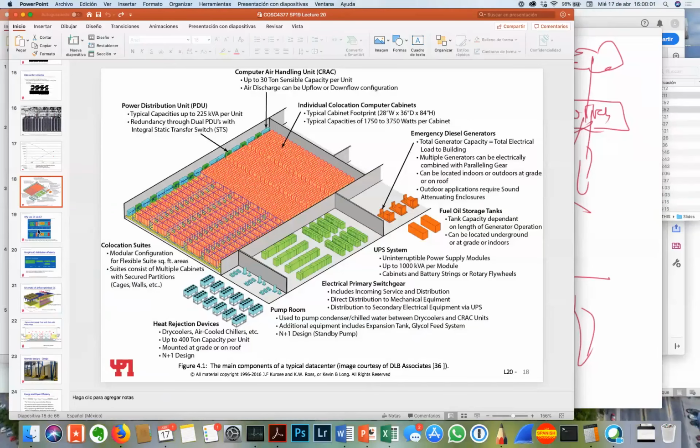So they're very dangerous environments, but this is how you keep the power conditioned, because the commercial power that comes in from the electric company is usually crap. This is why people try to get you to buy power surge protectors and things like that for home, which is a complete total waste of money, by the way. But at a data center, that power may not be smooth, so you'll run everything through the batteries to even it out and give yourself a perfect constant voltage. And if the power goes away, the batteries can run for a while, fire up a generator within 15 seconds, and switch that as your commercial source, and you begin recharging the batteries, and the power continues on through to the servers in the data center.